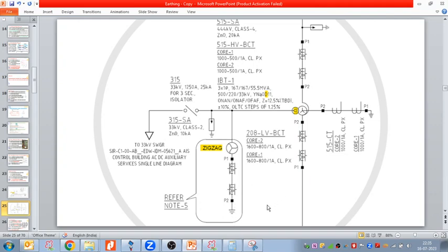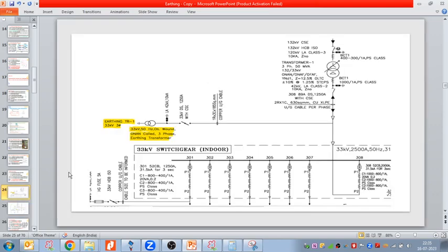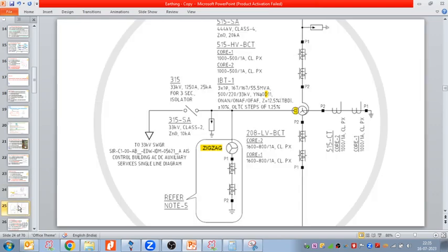When the current flows through this, here we will place the earth fault relays, and through that we can detect the earth fault current, and we can provide input to the protective relays to disconnect or isolate the system. So zigzag, here, is a two winding transformer, and this is the case of the neutral grounding transformer.